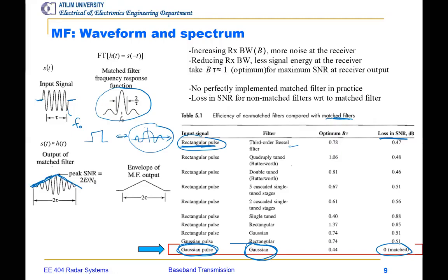Now, in the next stage, we simply take samples from this triangle. If there is an input signal, we get the high peak here. If we get noise only at the input, then this is going to be just noise. So the sampling process is based on taking a sample from this envelope signal and then comparing it with the threshold.